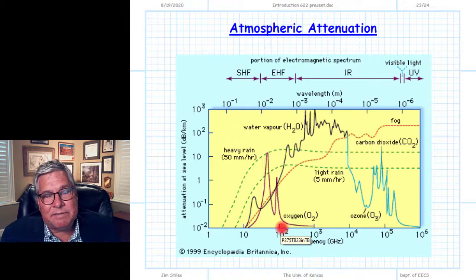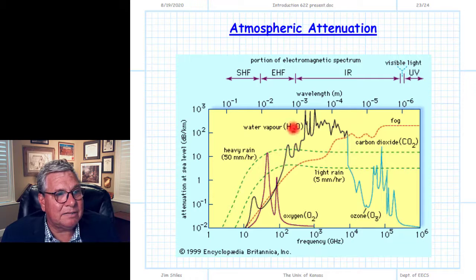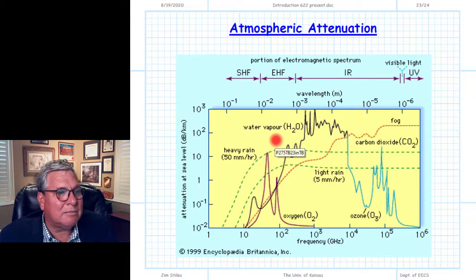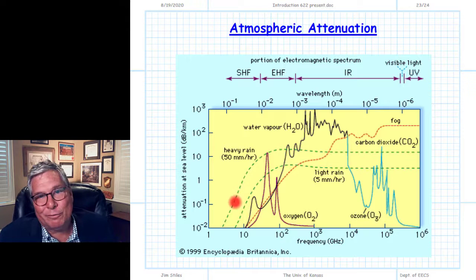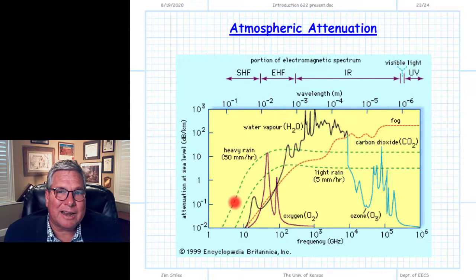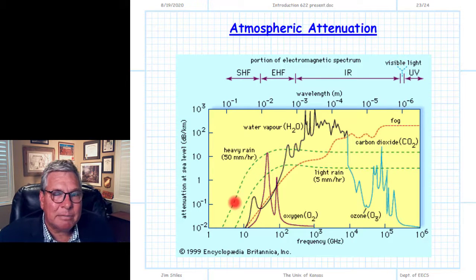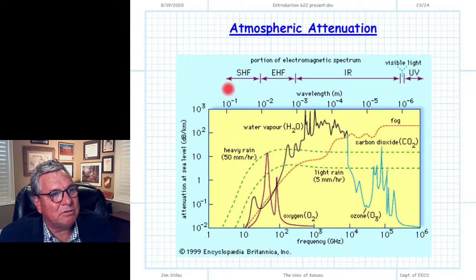What we find nowadays, 5G is trying to push into this region between 10 and 100 gigahertz, and they're doing this by keeping the wireless transmission distances small, to just a kilometer or less. But even then, they start to have a problem with rain. They don't advertise this, but your 5G system, if it starts raining really hard, is probably going to have issues, and that's why 5G has backup down in the lower frequency spectrum. So if rain does knock it out, they can switch to that and have diminished capability, but at least capability nonetheless. Interestingly, if you move along, you can see the different spectrums here.